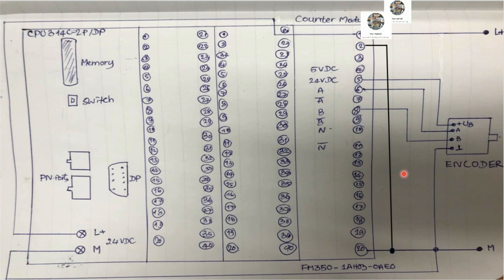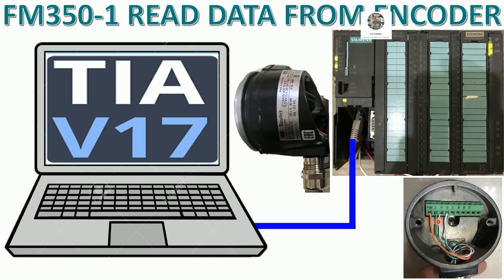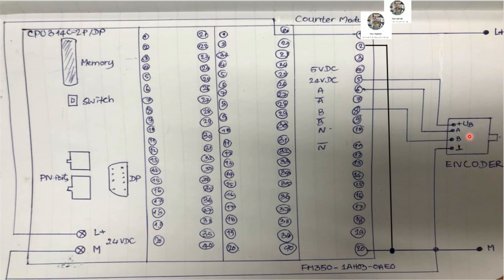So here is the overall drawing. I just drew the connection of the encoder to the counter module. This is the model number of the counter module and this is the encoder. We will use 4 terminals for the encoder, as I mentioned in this slide here: UB plus, A, B and 0 volt.